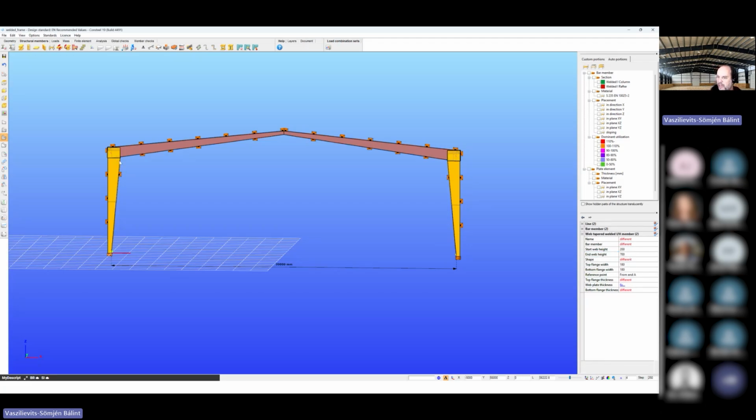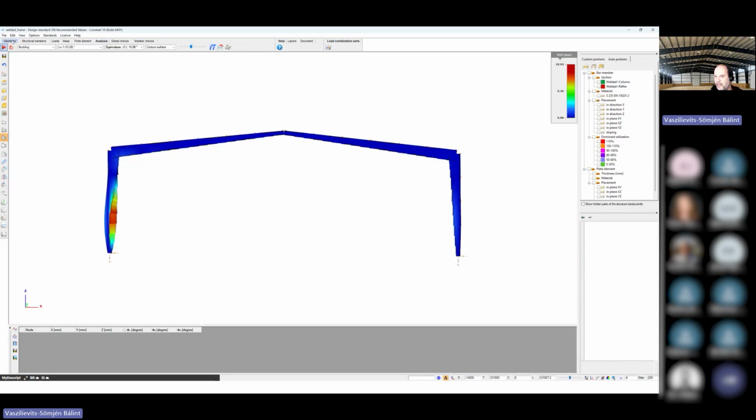The sections will be bigger to the inside, as I said, because I used this sort of relative system for the eccentric position. All the section changes can happen only to the other side. So the other side of the column became deeper, and I don't need to move the columns more to the inside, from the rafter to below the rafter, because the geometry is kept as desired, and I can do all the changes.